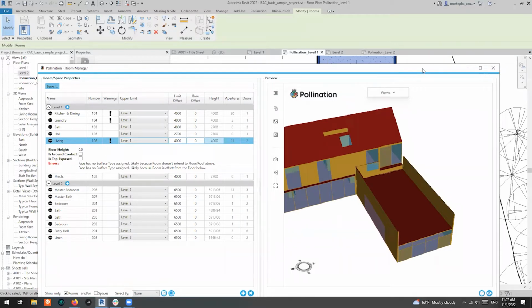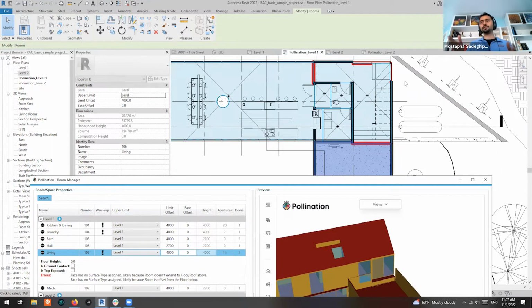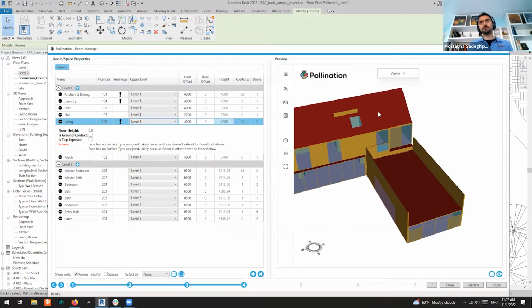So can we move the separation line? Is that a quick workaround? What I usually do is try to figure out where the leak is and just draw the separation line there. We can test putting it out there, but I think for this model we're going to have to test it, because even if you put it out there, you will see the leak in 3D. So you really have to fix the roof. But yeah, we'll get there. I know separation line is something that needs to be communicated, but you have a lot of flexibility to just go and draw separation lines in places where it's really needed.